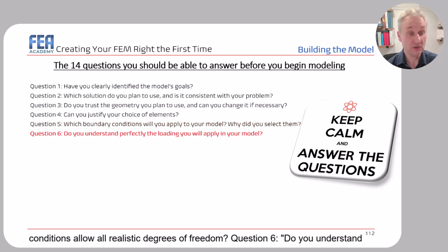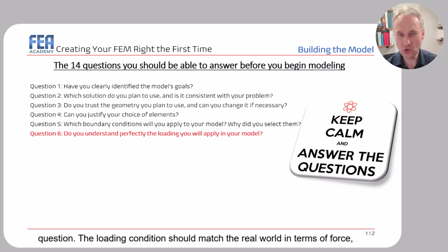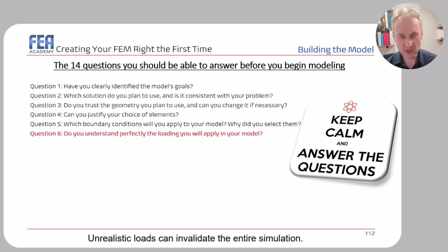Question 6. Do you understand perfectly the loading you will apply in your model? And it is related to the previous question. Okay? The loading condition should match the real world in terms of force, pressure, displacement, and stuff like that. Okay? Unrealistic loads can invalidate the entire simulation.